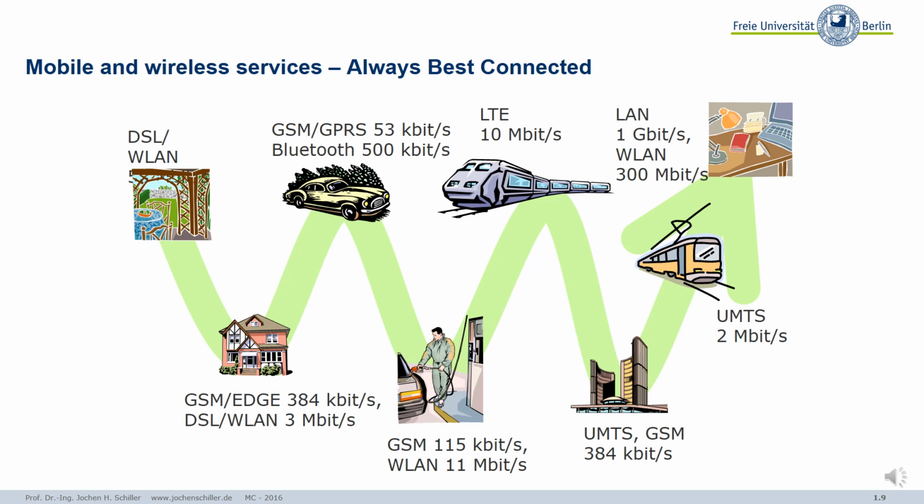That's it. You will not really notice it, but in the end, what should happen to the waves? Absorb. Also the trees. Now we have spring, that's worse conditions for mobile communications. Winter, better, no leaves. Because the leaves, depending on the size, roughly have the size of the wavelength of the waves, so they operate like an antenna.